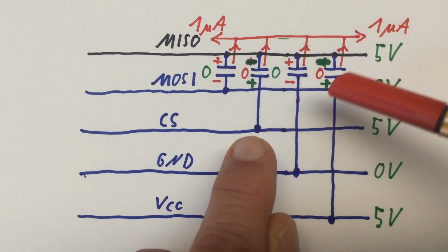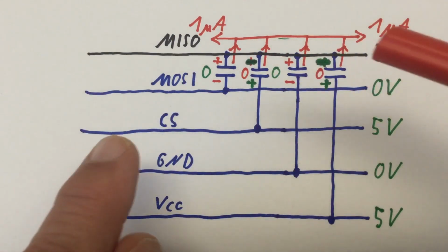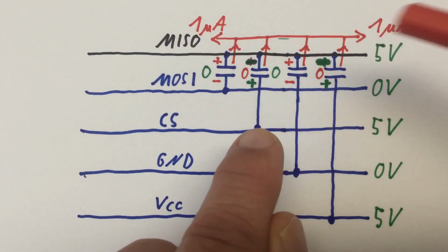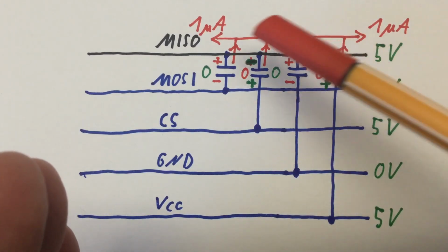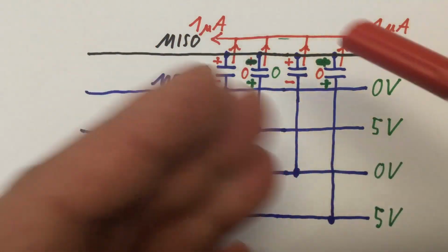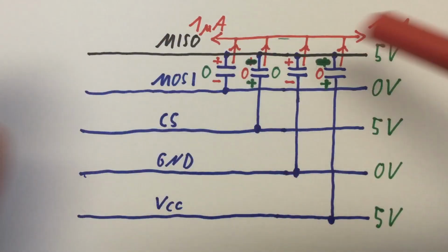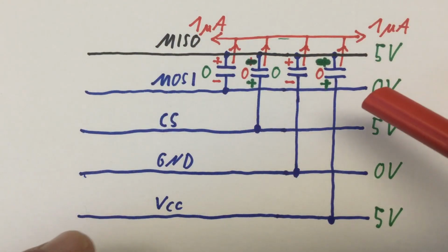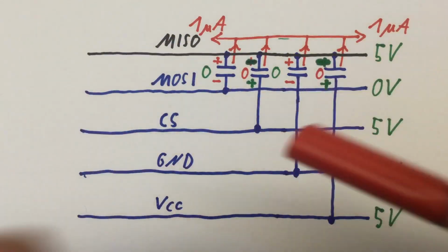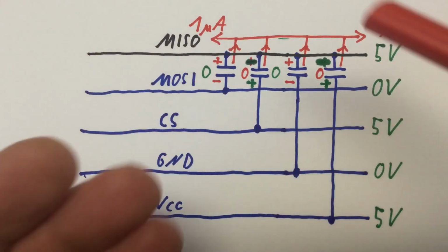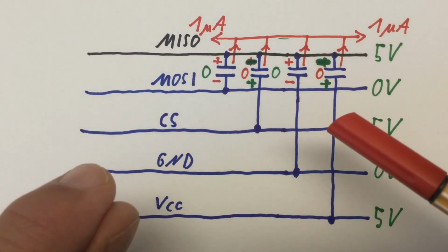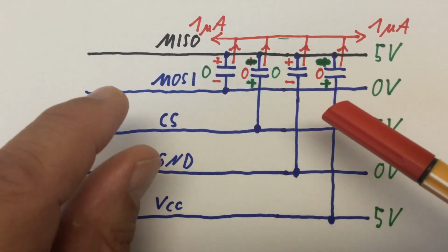Green plus minus, because in the end we have here a plus 5 volt line connected to MISO down at 0 volts. So all these capacitors contribute to the effect that we have here, stray capacitance on the MISO line, which obviously can be a problem if your data lines get very long. It was just nice to show it here with that extreme example using a 50 centimeter flat flex cable.